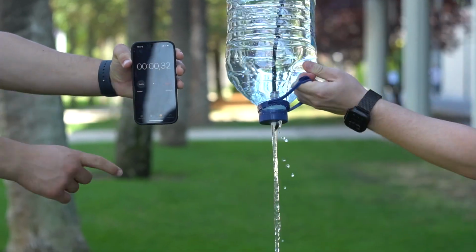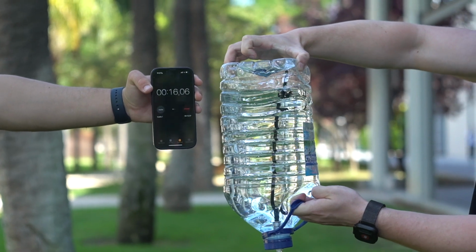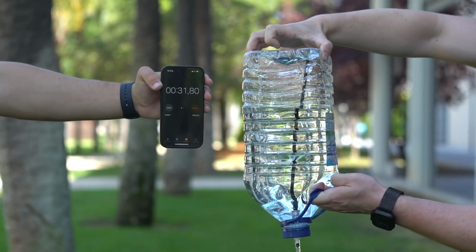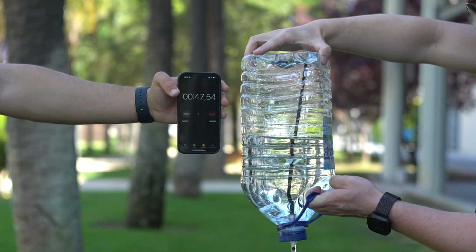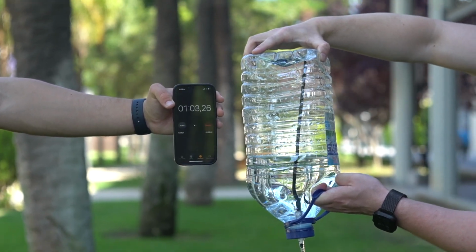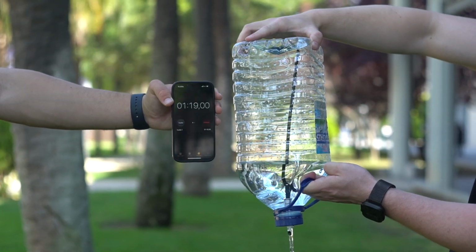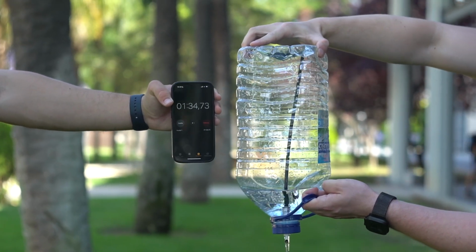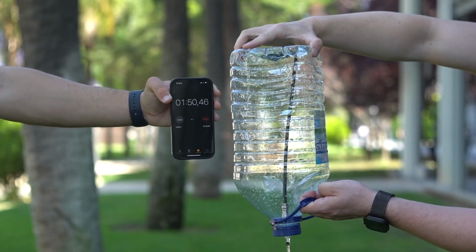Next, we tested the nozzle with a 2 mm diameter air intake hole. We observed that, even with this smaller diameter, a sufficient amount of air was still entering the bottle, as it did not show any signs of compression. Using this nozzle, we recorded a total drainage time of 1 minute and 51 seconds, which is quite similar to the result obtained with the 3 mm diameter air intake. This suggests that the size of the air intake hole does not significantly affect the overall drainage time. Based on our calculations, the theoretical drainage time was 57.57 seconds, resulting in an efficiency of 51.86% for this nozzle.